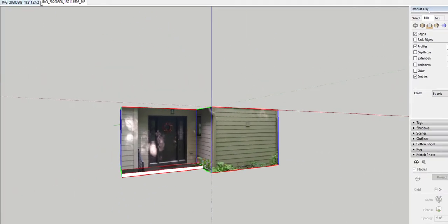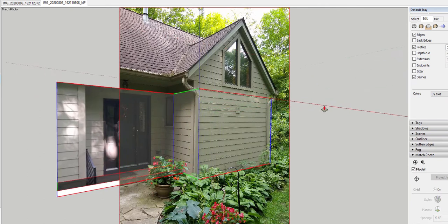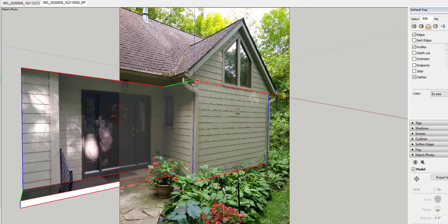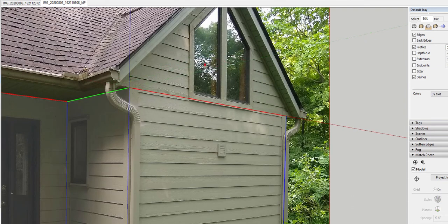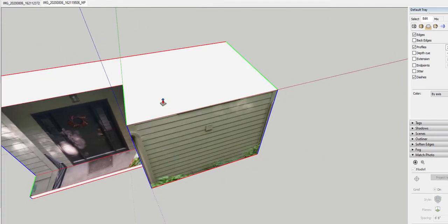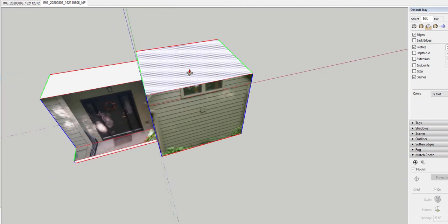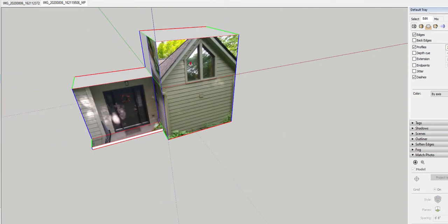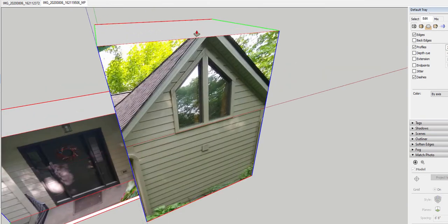Okay, let's take a look at the image here. So at this point, I'm going to want to come up the height and also get this overhang working for this peak. So I'm going to draw a line right here. Just break the surface. I'm going to pull this up in the blue here to where the peak is.